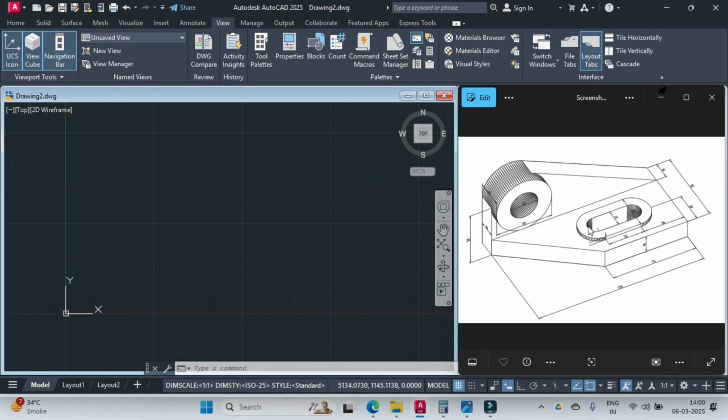So we'll begin by drawing one circle of 16 dia, copying it at a distance of 32 units, drawing two quadrantial lines, trimming the unwanted circles, and joining it and making it into one structure. Then offsetting it outside to a distance of 8 units because this total dia is 32 units.